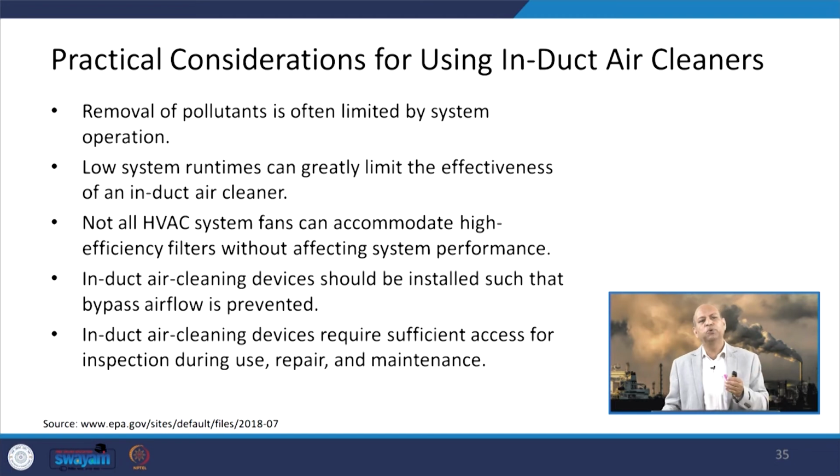Well, then removal of pollutants is often limited by system operation, and low system run times can greatly limit the effectiveness of an induct air cleaner. So, the system has to be designed properly so that it has sufficient time. Then, not all HVAC system fans can accommodate high efficiency filters without affecting system performance. So, it is a kind of trade off. You have to see where you can install it and run the HVAC system properly so that it does air conditioning as well as removes the pollutants.